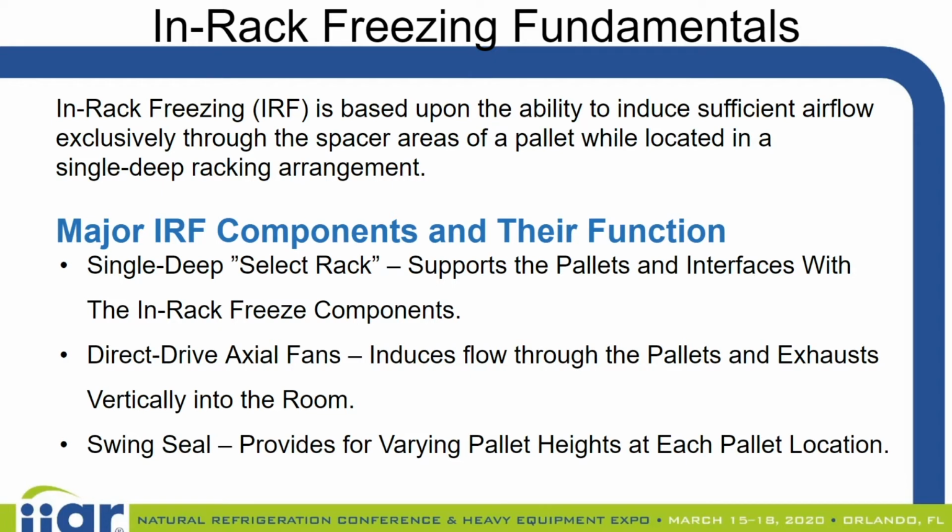So in-rack freezing, like I said, is really based upon the ability to induce sufficient airflow exclusively through the spacer area of a pallet while located in a single deep arrangement. So that one sentence really encompasses much of the thought process in the development of quick freeze or in-rack freezing.